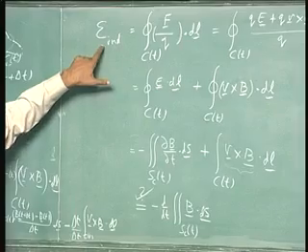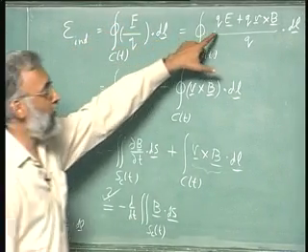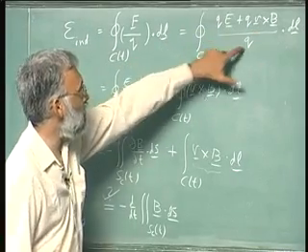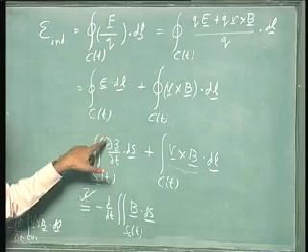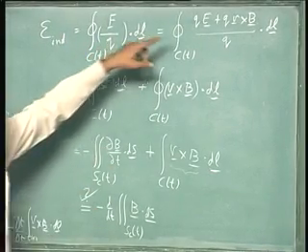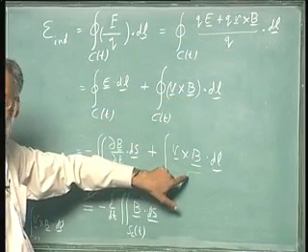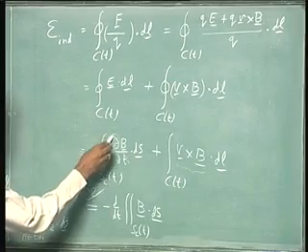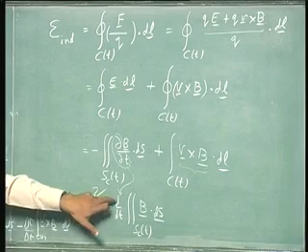I can start with just the force equation on a charge. Force equation says QE plus QV cross B. The QE portion gives me transformer EMF, the del B del T over a fixed surface. The QV cross B gave me a V cross B dot dl, and that piece is precisely the piece that will take this del del T and move it outside into a d dt.